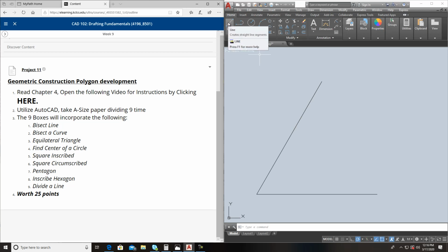And then, this is the most important. If you're on the board, you have to hit line. You click on that point to that point, and you draw that in. This is your most important line here, and the reason I say that is because you're going to set your compass to that, your protractor head to this, and then you're going to move it and catch those endpoints of those lines or those points.